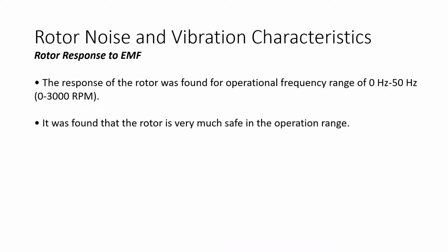For a practical analysis and to reduce computational cost, we found out the response of the rotor for the operational frequency range of 0 to 50 Hz or 0 to 3000 RPM. And we found out that the rotor is very much safe in the operating region.